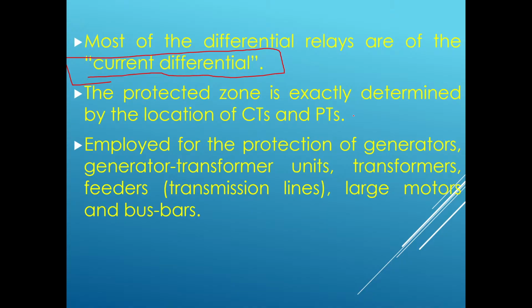There will be a comparison between the entering current and the leaving current of this differential relay. If the current entering the relay has a phase displacement with respect to the current leaving it, and if it exceeds the predetermined value, then this relay will operate.